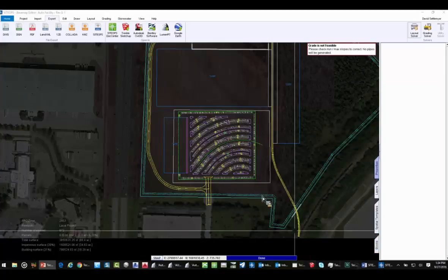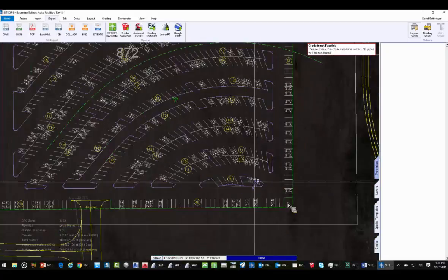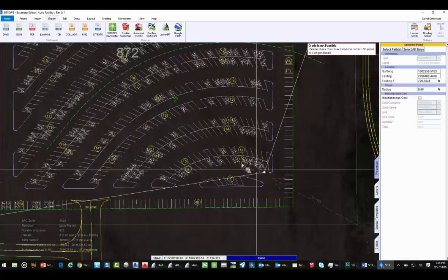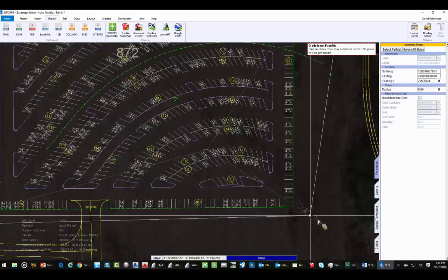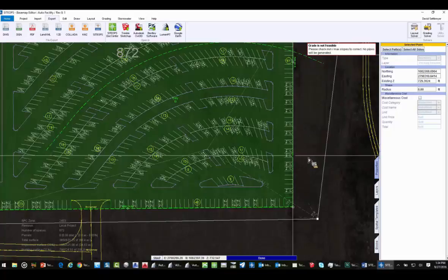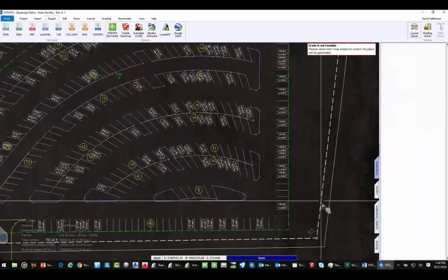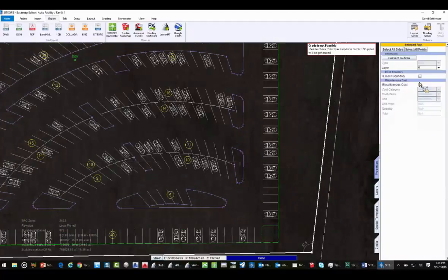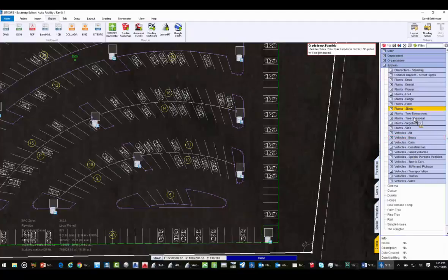Okay, what this does is this is just an area that assigns where to put those cars. So for example, if I didn't want the whole parking lot coverage, I can move this. It gives the user the ability to control, because maybe I want a whole bunch of one car, but only little pocket areas of another. It could be something like this. Let's come in and let's offset this. We'll just bring it over a little bit more. Maybe in this case, instead of a car, I want it to be an island, and I'm going to bring in a tree.